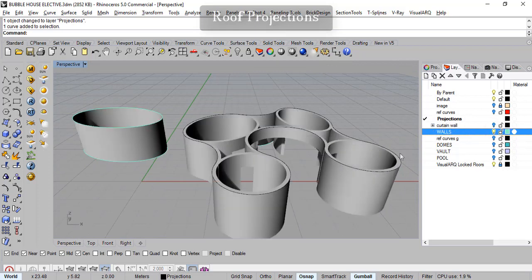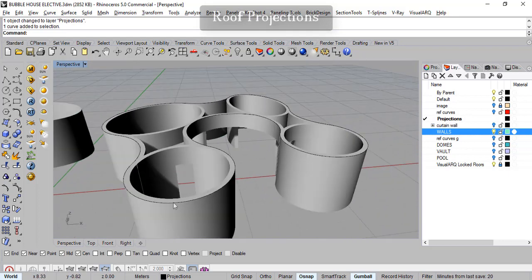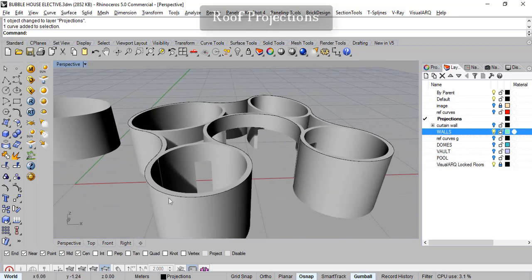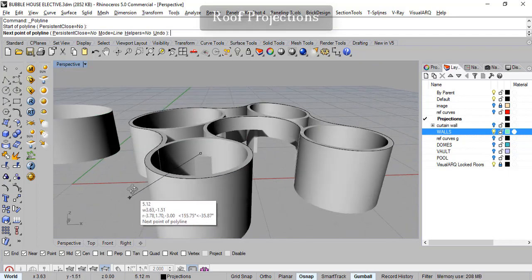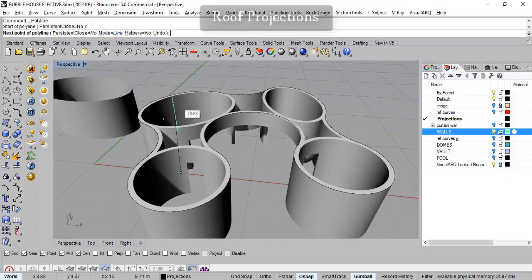Now if I put on the walls layer, it's exactly on top of the walls layer on the exterior perimeter edge, and we need to create a profile here perpendicular to this wall. How we can do that is by simply creating a line first from the center of this, like this. But the minute I draw a line it jumps to the ground floor. It doesn't allow me to draw exactly at this level.